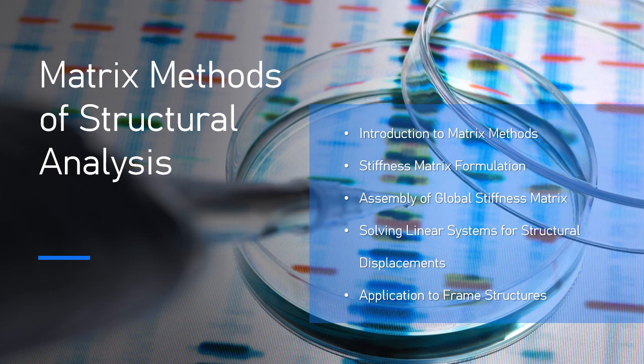matrix. 4. Step 4. Apply boundary conditions, e.g., fixed at one end, free at the other. 5. Step 5. Solve the system of equations for the displacement vector U. 6. Step 6. Compute internal forces and moments in each element from the displacements.